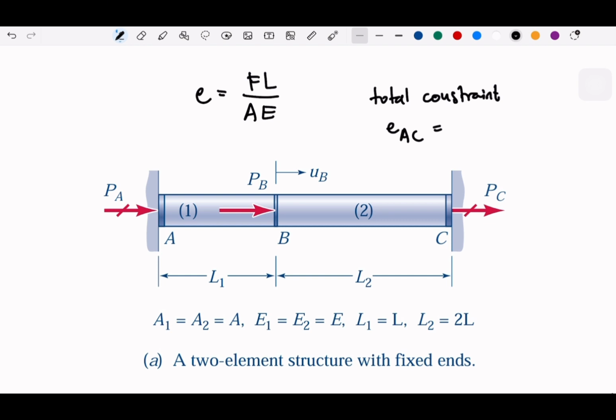Imagine this wall cannot be moved, so the wall stays as it is. We could imagine that there will be a small displacement here, but the whole thing will stay as it is. There will maybe be something going forward here, but another reaction is going to cancel that out, so that the whole elongation will still be 0. And that's what we call the compatibility equations.